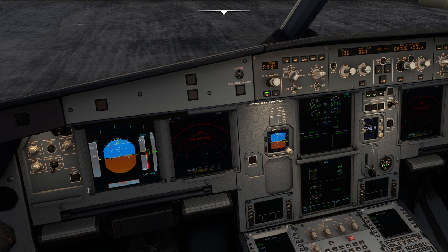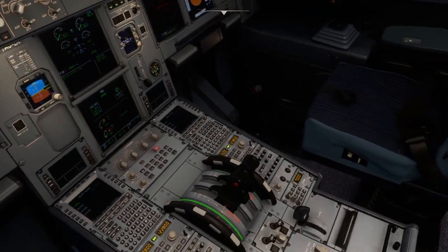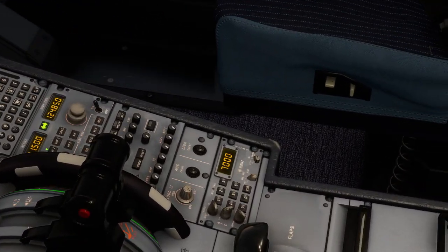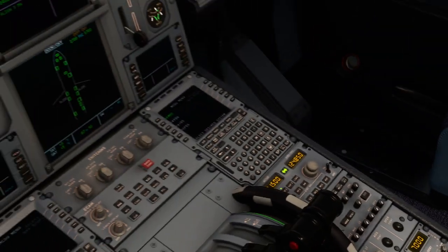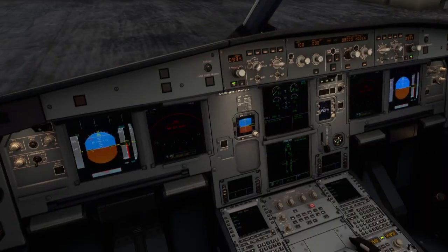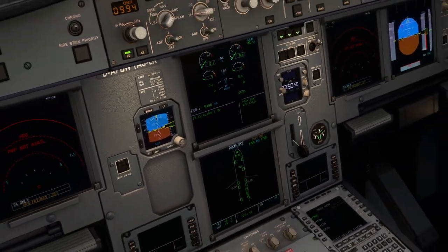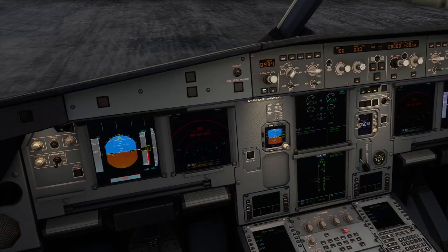Altitude is set. Then I have to configure QNH, okay, and then I need to configure my PFD. But before that, I need to confirm whether my transponder configuration is correct. It looks like it's correct, but it shows TA only. But let's give it some time. It's on now, and I think still there are 3 minutes to go for the IR alignments, and let's wait until it is coming up.